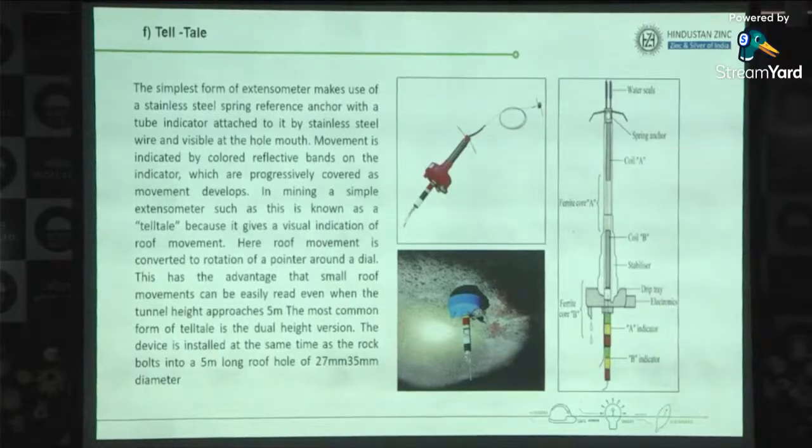To find out whether deformation is really happening in the cold joint or not, we are putting this telltale. We are installing the telltale in a 10 meter long hole. If any deformation happens, we can get the data through the telltale.